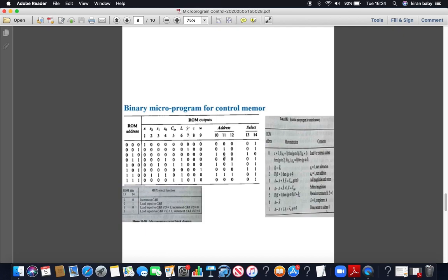In that you can see that only the Y bit is being set. When the sign bit of the B register is complemented, we learned from the previous video that it is the Y bit that needs to be set. So that is the reason why only Y is being set and all others remain as such.